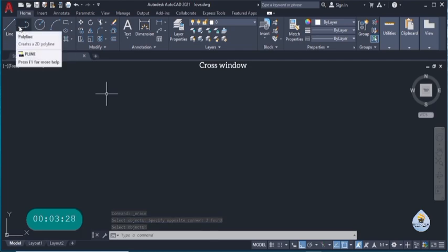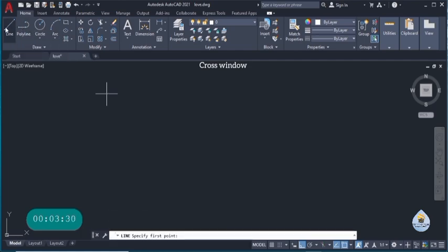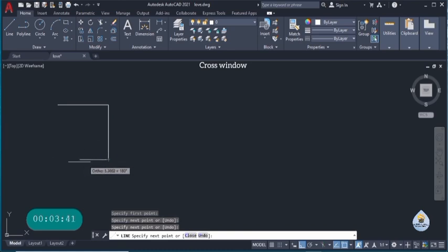If I take my line this way and click the first point here, then the second point, I didn't really take any dimension, and I want to draw this. I didn't know the length. I can easily move my cursor to this end here, then bring it down. You see my polar tracking is on. So I'll connect these two together. Click enter to end it.